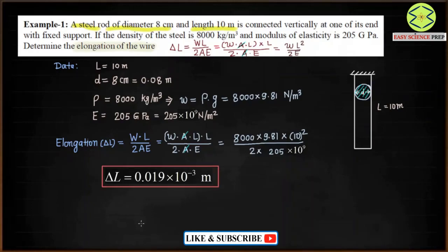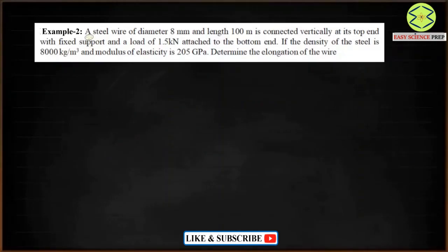Okay, similarly we can take one more example to understand. So let me show you the next example. We have a steel wire of diameter 8 mm and the length of the wire is 100 meter. It is connected vertically at its top end to a fixed support, and a load of 1.5 kilonewton is attached to the bottom end. If the density of the steel is 8000 kg per meter cube and the modulus of elasticity is 205 gigapascal, determine the elongation of the wire.